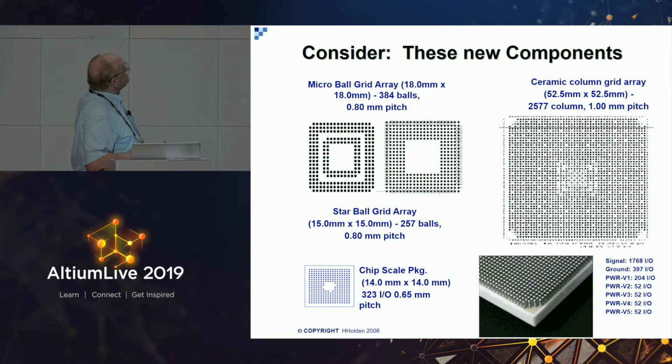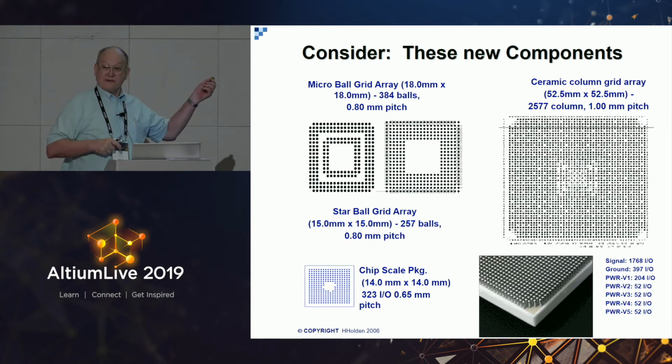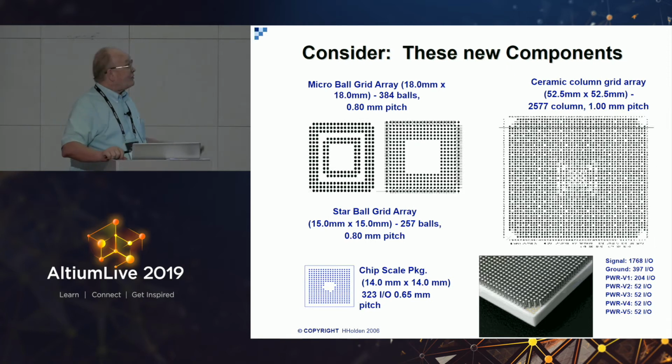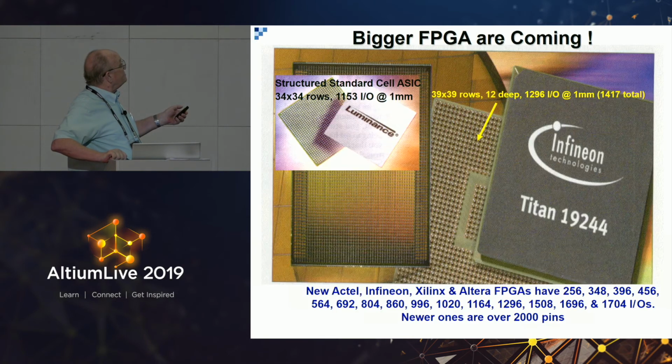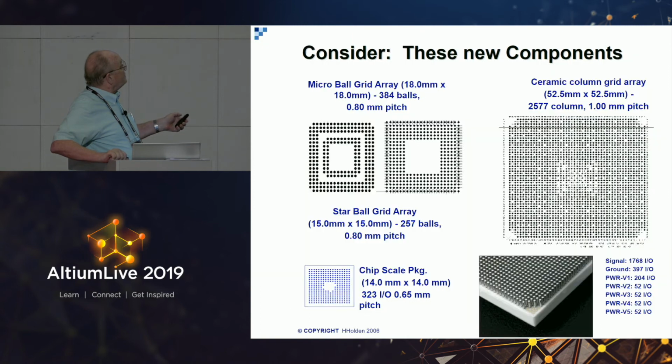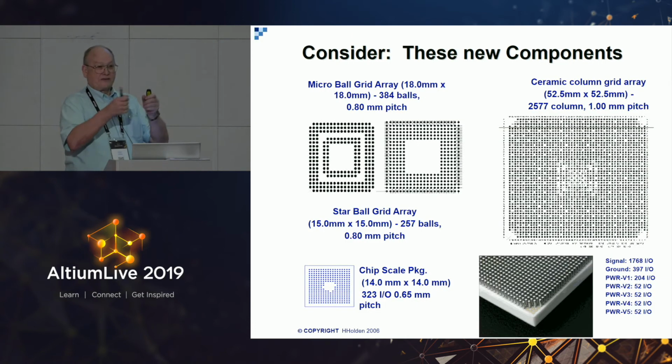And here is this ceramic column grid array. These columns are 95% lead, so they are exempt from the European standard on lead-free. Europe does allow lead in electronics, but only in semiconductors. The reason was, if they forbid that, there'd be nothing flying and nothing driving, because the medical, military, and aerospace sectors have not found suitable substitutes for lead in terms of ductility.